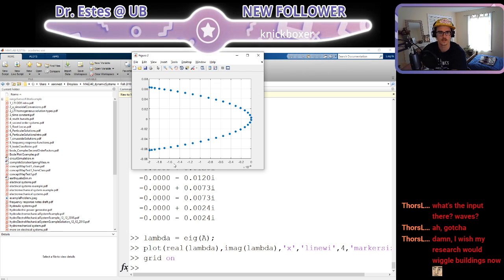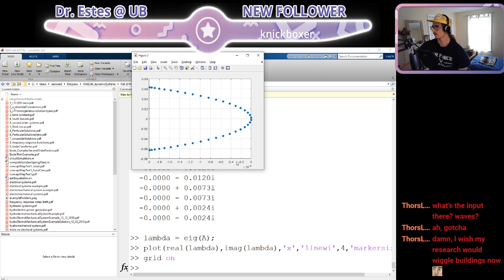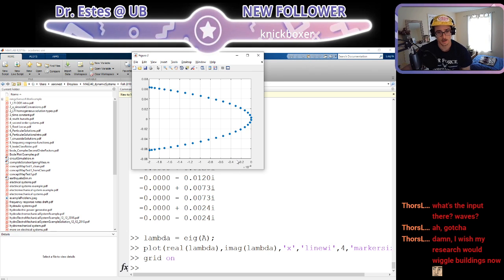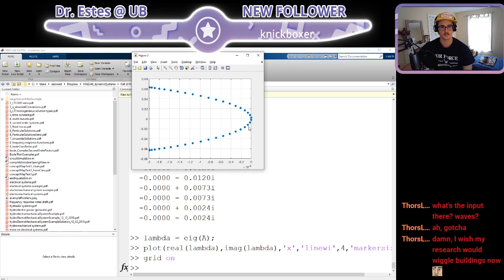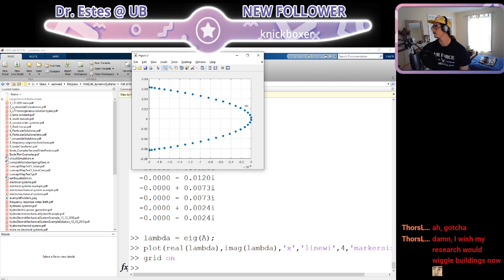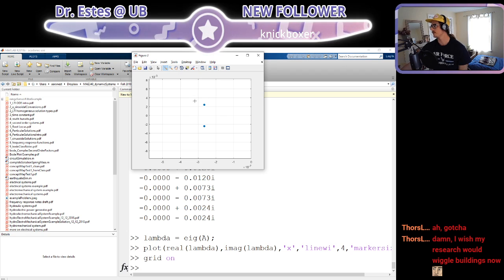All of them have negative real parts, so the system's stable. Which ones are the dominant roots? Well, the ones with the smallest real part. So they're going to be over here. So these 2 would be the dominant roots.